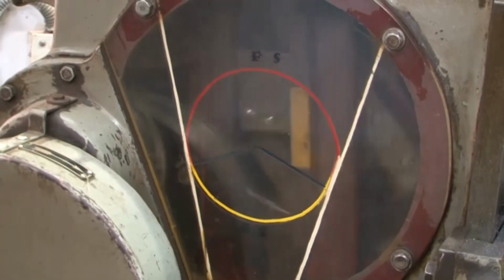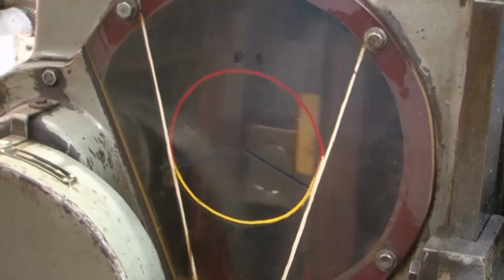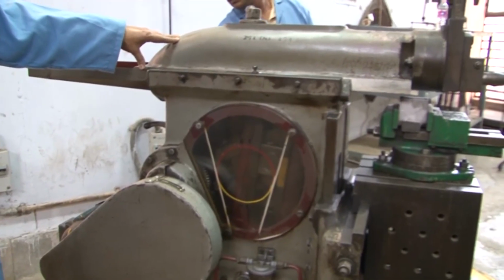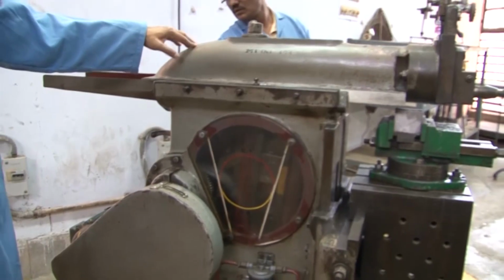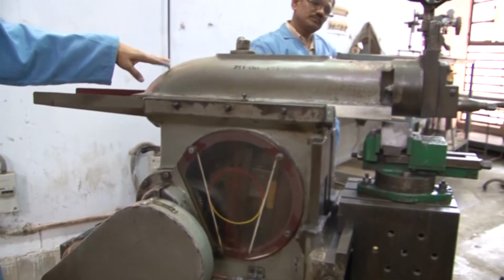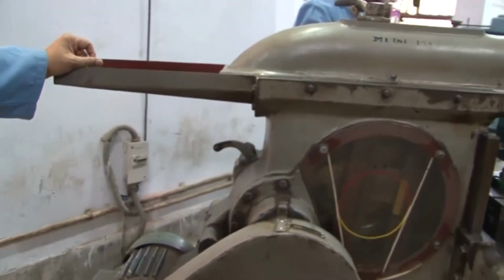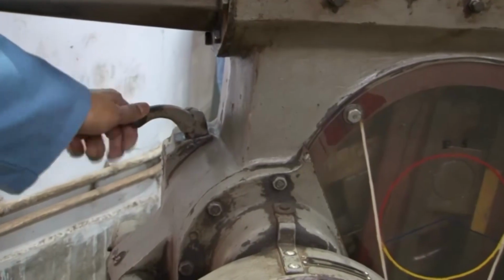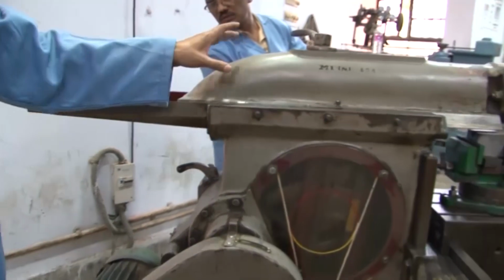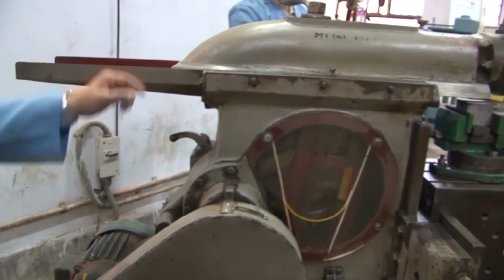You can see the working principle of the bull gear and the arm, and overall the Whitworth quick return mechanism. Now, we have shown you how the stroke length can be increased, but also the speed, that means how fast the ram will be moving, can also be changed. Here we have 3 speeds, that is 82, 48 and 108. Depending on the position of this lever, we can have a higher stroke speed and a lower stroke speed. For comparison, right now we will have 82 speed.